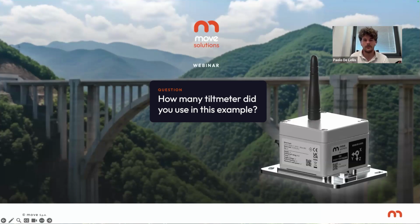But of course, we recommend, if you have, for example, a beam that is more than, I don't know, 50 meters, to use 6 sensors or more for the analysis of the deflection.